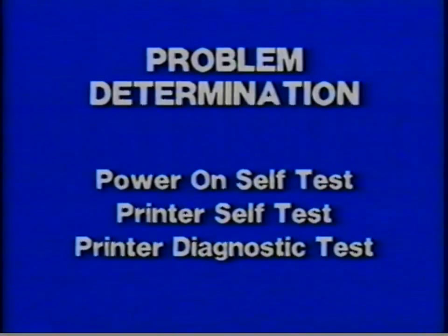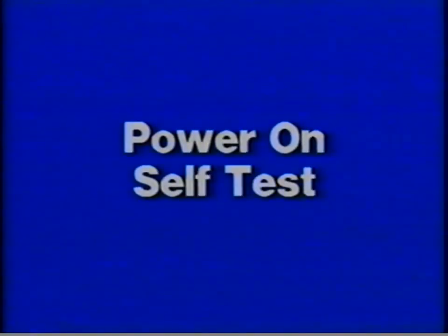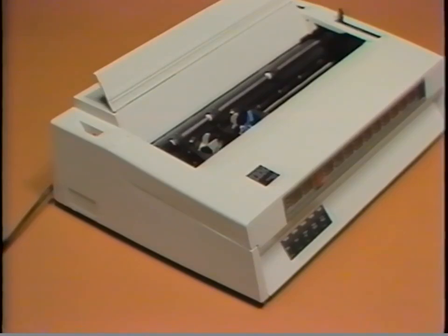There are 3 tests to help the operator with problem determination. They are the power on self-test, the printer self-test, and the printer diagnostic test. Each time the printer is turned on, it runs a power on self-test. This test is an important diagnostic aid.